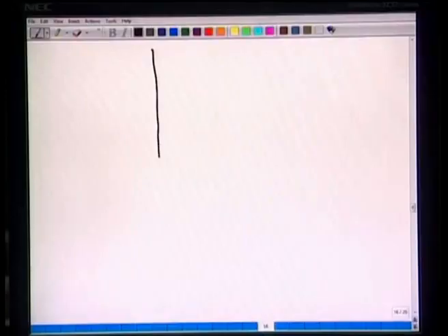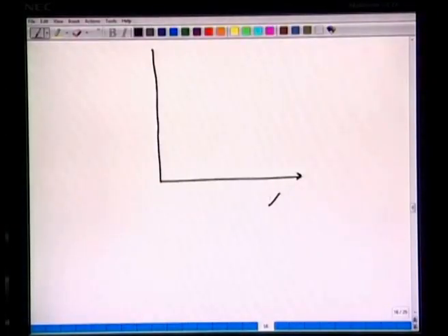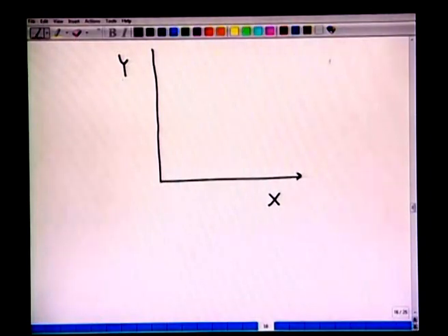Now, let us mark our points x1, y1, x2, y2 on the equilibrium curve and draw the operating curves. So, we have the same capital X, capital Y, which will be equivalent to some small y and small x, different ways of drawing the equilibrium curve. So, we can draw, say, an equilibrium curve like this.